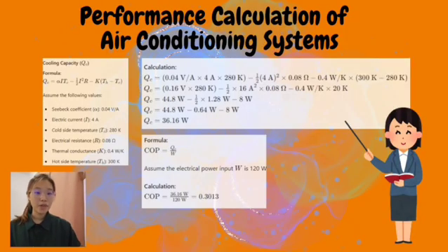We have three main formulas we'll be using, that is QC, cooling capacity, ZT, figure of merit, and COP, coefficient of performance. In simple words to conclude, ZT is the material efficiency in converting heat to electricity. QC measures how much heat the cooler can move. COP measures the overall efficiency of the cooling process.